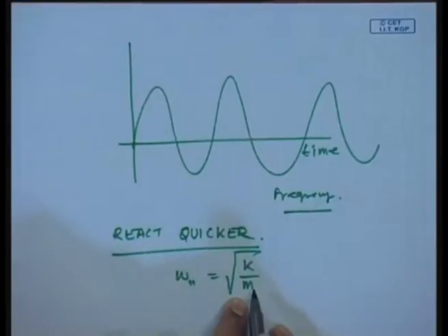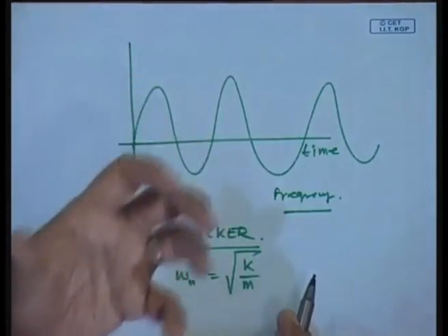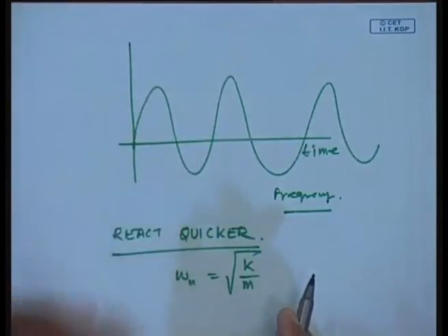Okay. So, that is why jockeys are of lesser weight. By the same token, if my mass is very heavy, the transducers will have a very poor frequency response. They cannot react faster. We all crack jokes about persons who are overweight; they have a poor reaction time because of this. Similarly, transducers which are heavy and bulky cannot respond fast to the mechanical parameters which they are sensing.